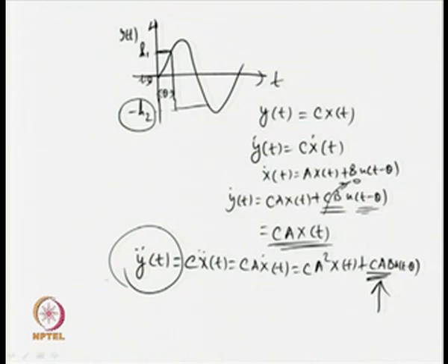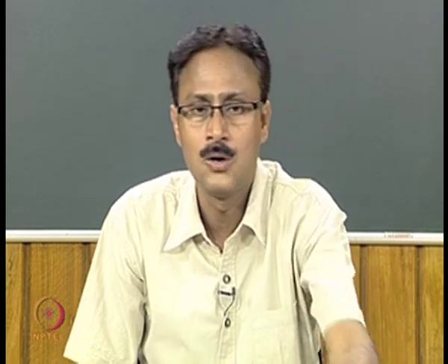So, analysis also shows that there will be abrupt changes in the second derivative of the output signal at certain instants of time, and if that time can be tracked correctly, then information about the time delay of the process can be obtained outright. And this is how one parameter of the transfer function model can be obtained conveniently from the derivative of the output signal.